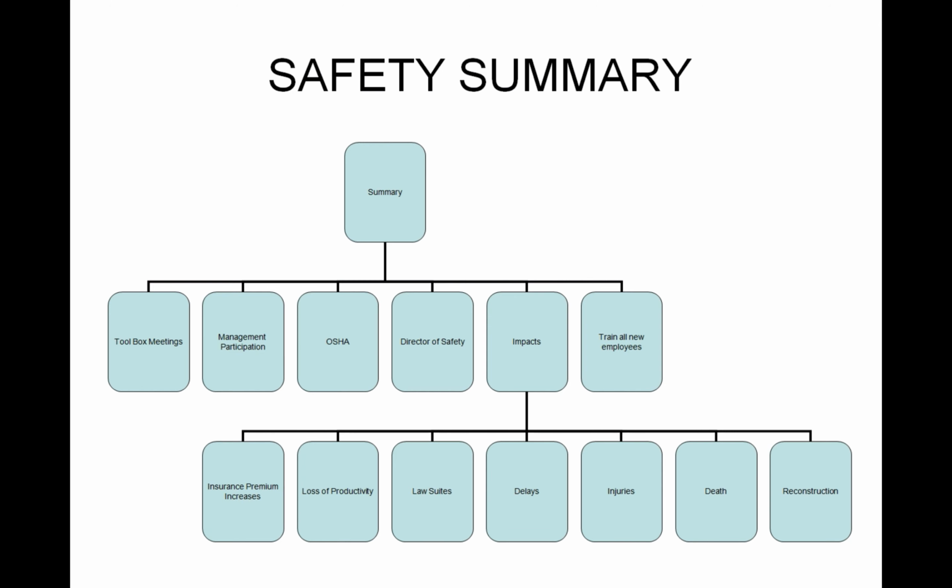The CM, the PM, they have to keep an eye on the weather. If you know there's a pending storm coming, you have some notice, you have a couple of hours. Number one thing you do is shut things down with the crane. It's not worth taking the risks of having a major accident. Let's get the booms down, or let's secure it. Do what you need to do per the manufacturer's recommendations to have that crane secured, and then wait for the storm to be over and get back to work.